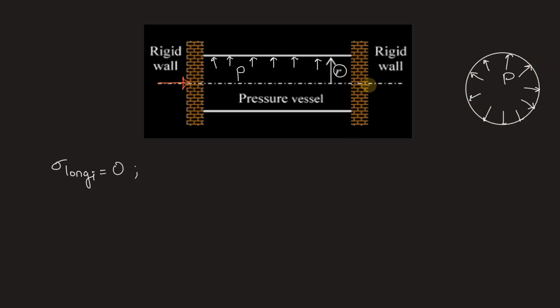From both the sides we can see that the cylinder has compressed. Because of this compression, the cylinder might fall down, or there might be a gas leakage from the gaps that will be present between the wall and the cylinder. And that is why the cylinder is heated. Heat that is given to the cylinder creates a temperature difference of delta T. Coefficient of thermal expansion of this material of the cylinder is alpha, that is given. And we have to find out what is that minimum rise in temperature that we have to create so that there is no leakage of gas from this cylinder. That means there should be no gaps between the wall and the cylinder.